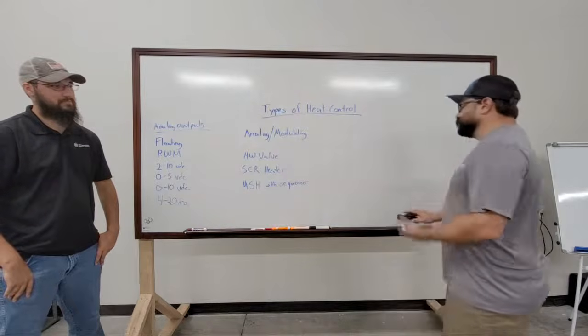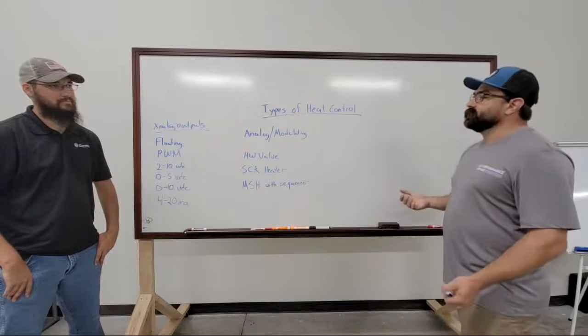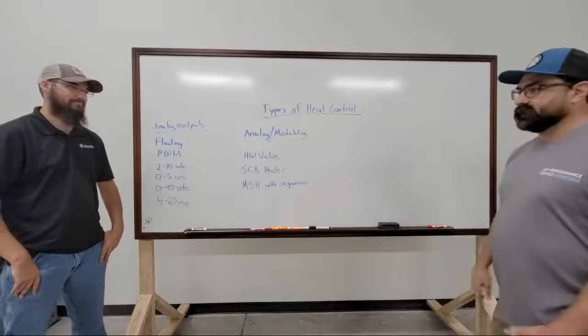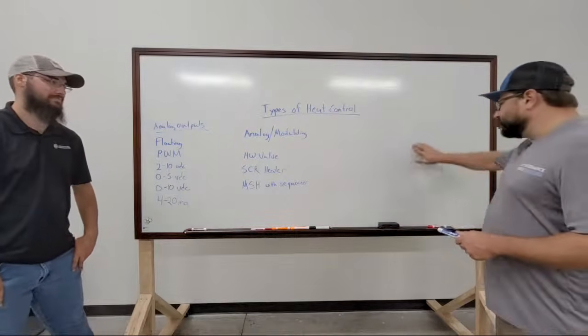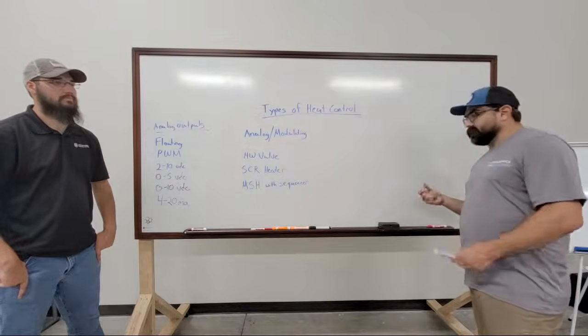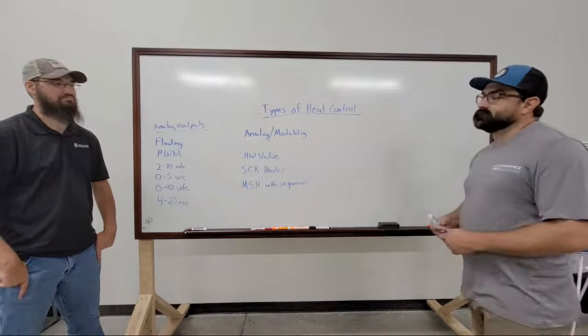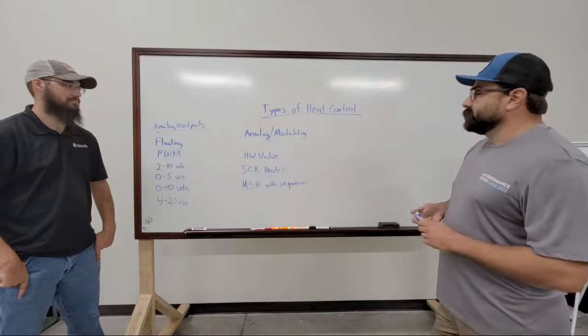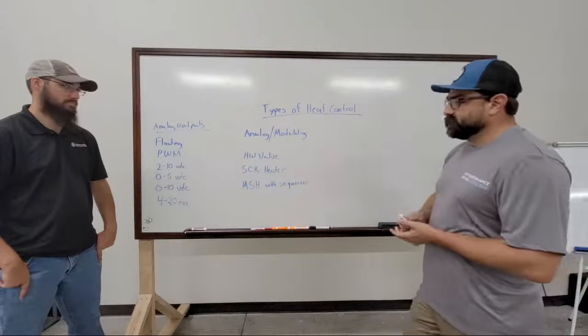But it would have been nice if that controller had a universal output that could have sourced its own voltage, and then it wouldn't have been a problem. But it did not. Honeywell does not have an output that is capable of that. So, oh well, no big deal. So that's pulse width modulation.